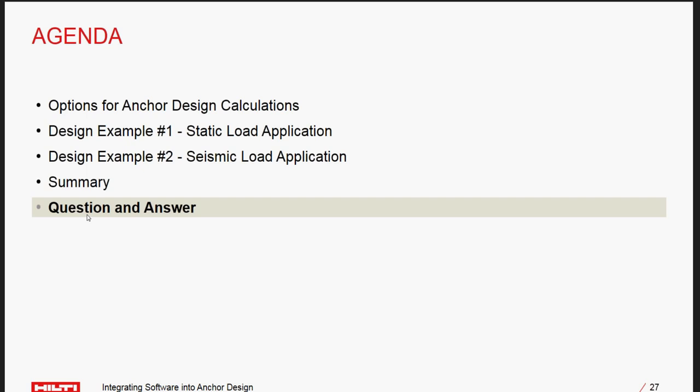In addition, moving down to the results section, we have an additional seismic phi factor that's being applied to the design. This tells you as the design engineer that this software is using these bond strength provisions from ACI as the basis of the calculation, and it's using these variables and taking this into consideration. Here's the result of the design bond strength capacity at the bottom of the screen. So again, the software is very well laid out. We're able to see transparently what the software is doing and what it's taking into consideration when we're walking through the design.